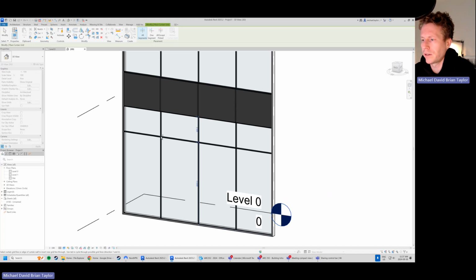I wanted to do this because I know in our best in town example, we've got the curtain wall, but then we also have a door within the curtain wall itself. Curtain wall door functions very similar to a curtain wall panel. Got to be careful here because in most cases, you're going to be using a curtain wall door family within a curtain wall. You're not using a standard door, you're using a very specific type of door, which in this case is a curtain wall door.